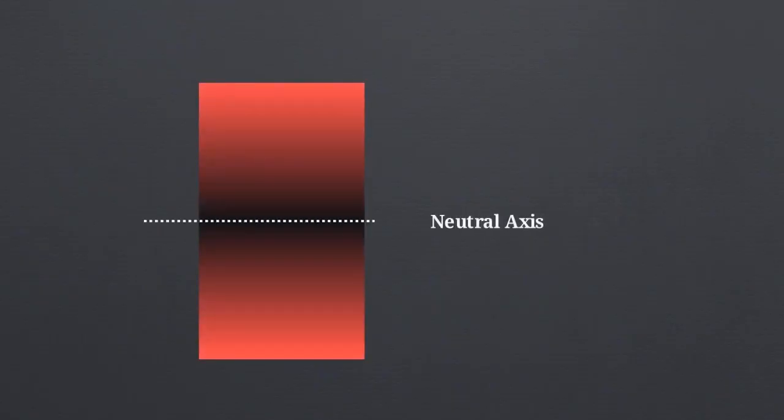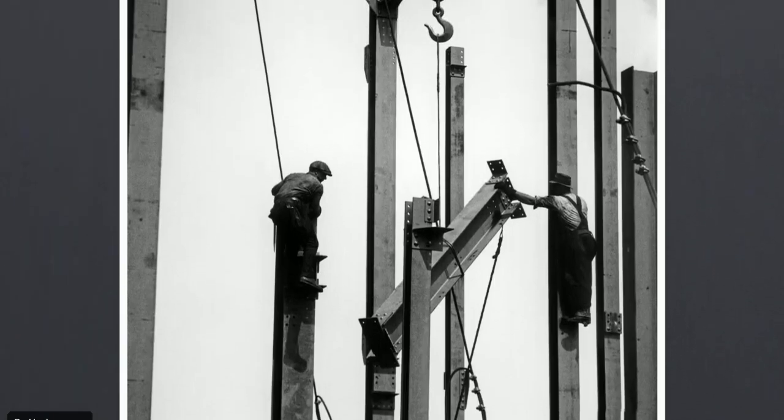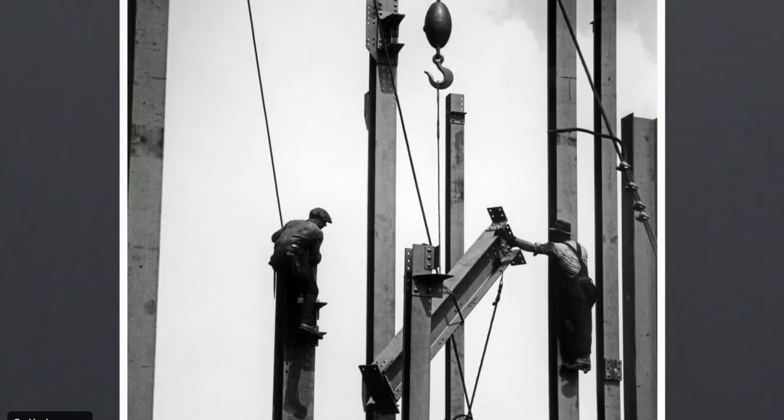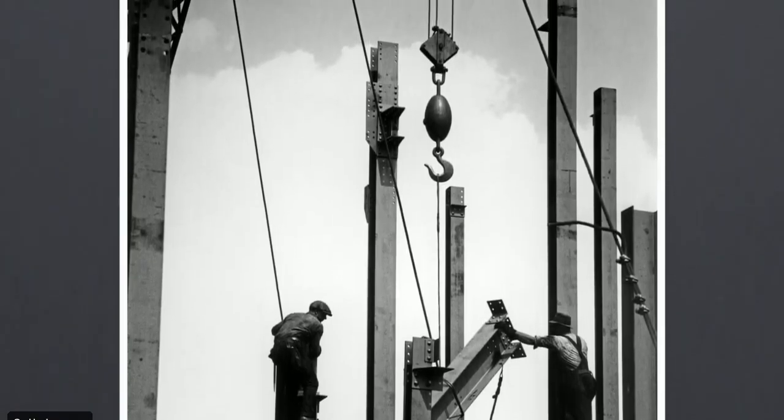This reveals a massive inefficiency in solid shapes. The material near the neutral axis carries almost zero stress and does almost zero work. The I-beam exploits this linear stress distribution. Moving lazy material from the center to the extreme flanges maximizes the section modulus without adding extra weight.